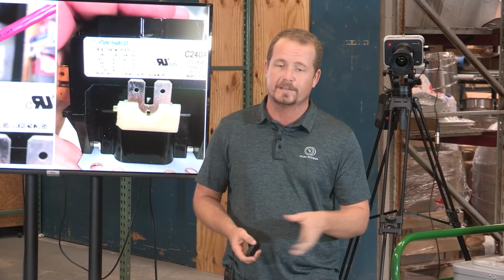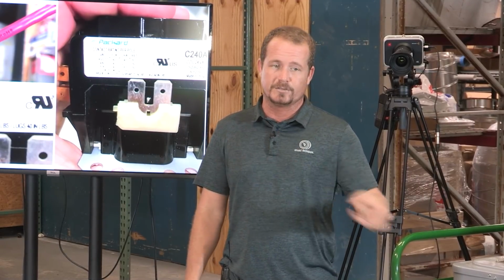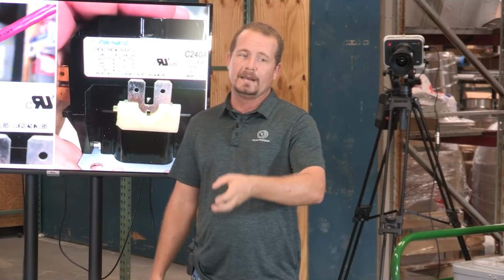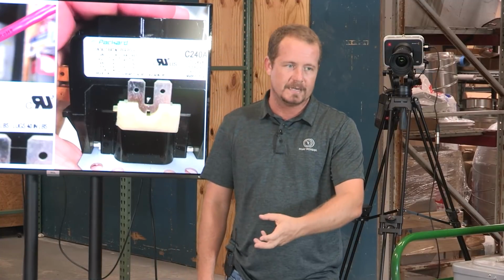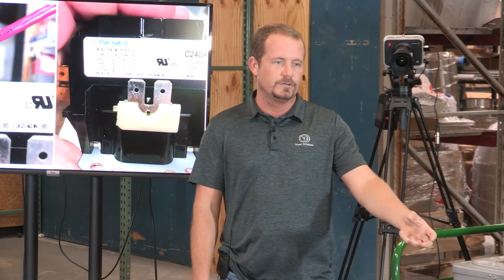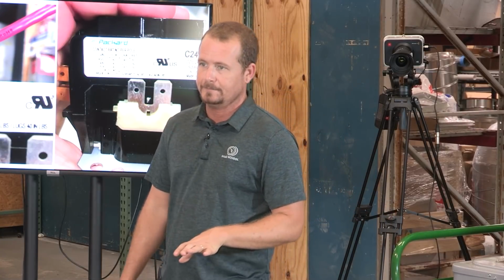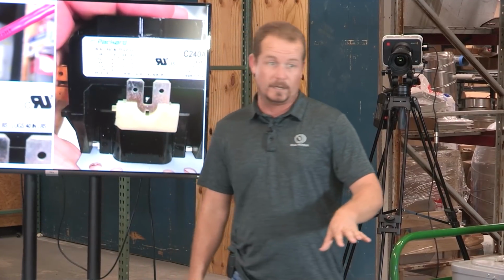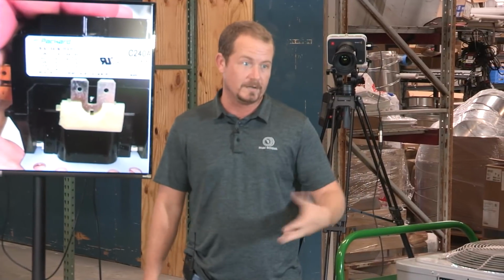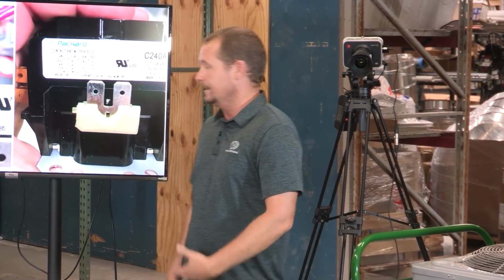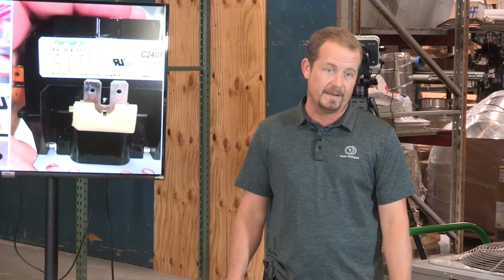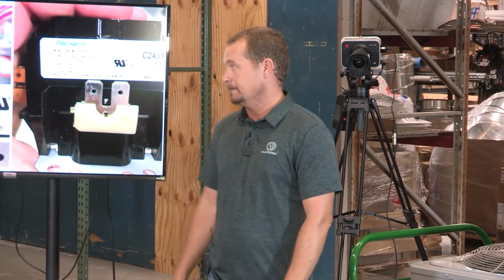So this is actually an interesting thing. If you pay attention to residential single-phase units, they may be rated at 14, 15 SEER, but when you connect it to a 208 power supply, it actually derates its capacity and its efficiency. So it doesn't work as efficiently, and it also doesn't have the same capacity when you drop that voltage because the motor actually slips more. It's not actually spinning as fast. The synchronous speed actually decreases. It's not a lot, but it's enough that it does affect the capacity and the efficiency of that unit.